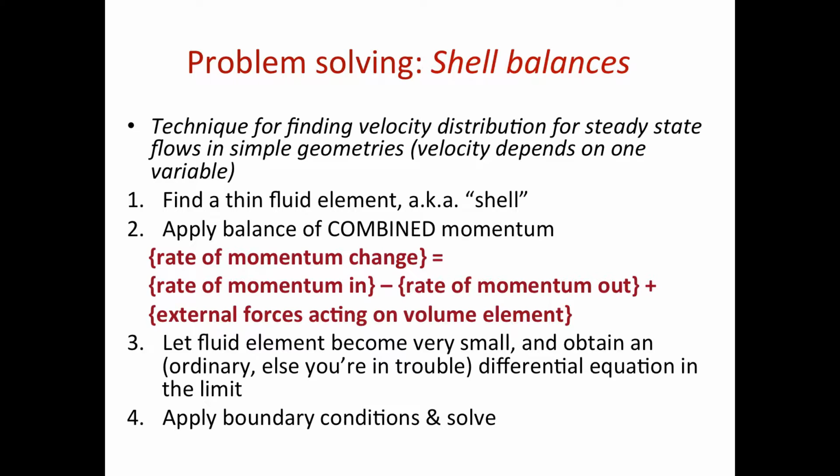So we basically find a little shell in the geometry. The shape of the shell will be dictated by the shape of whatever it is that I'm solving in, and my coordinate system will be dictated by that shape as well. The simplest one is the Cartesian coordinate system, but today we're also going to have cylindrical and later on spherical. These curved coordinate systems are a little troublesome to deal with when we're solving problems. So always remember to look up the formulas whenever we're looking at the stress tensor and so forth. It's just easier to look up until you become really confident that you know what those terms are.